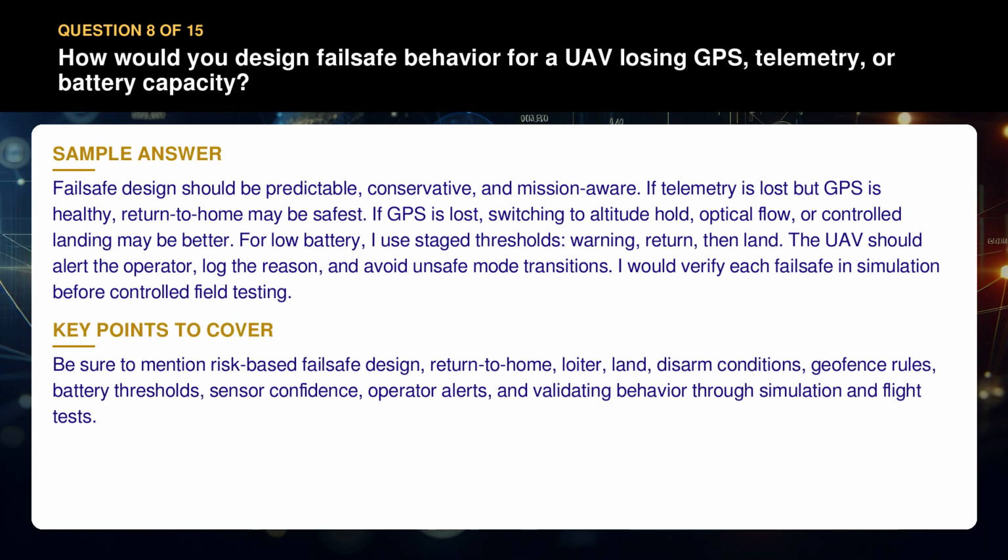Be sure to mention risk-based failsafe design, return to home, loiter, land, disarm conditions, geofence rules, battery thresholds, sensor confidence, operator alerts, and validating behavior through simulation and flight tests.